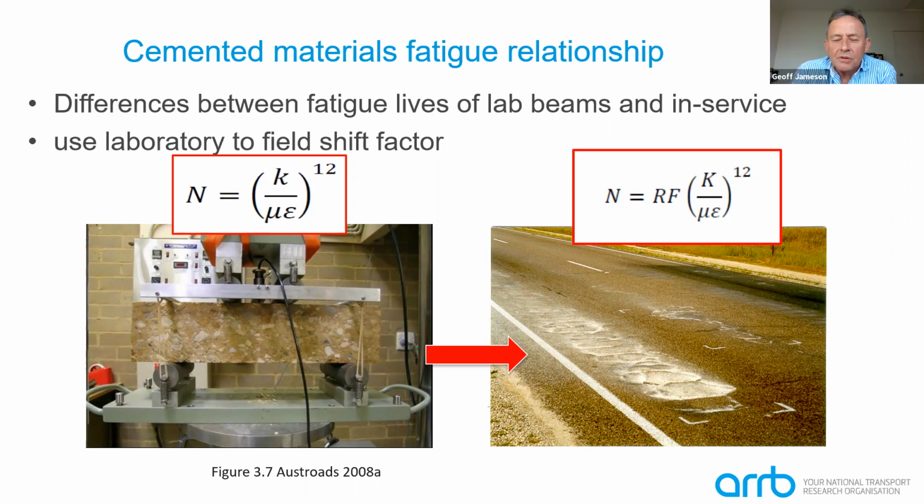Sorry, can you run through it again, please? Was the block cracking distress in the photo for a pavement with a thin asphalt surface overlaying a cement-treated base? I'm not quite sure what the question is, but basically that photograph looks like a thin asphalt surface, or it could be a sprayed seal surface, on a cement-treated base pavement.